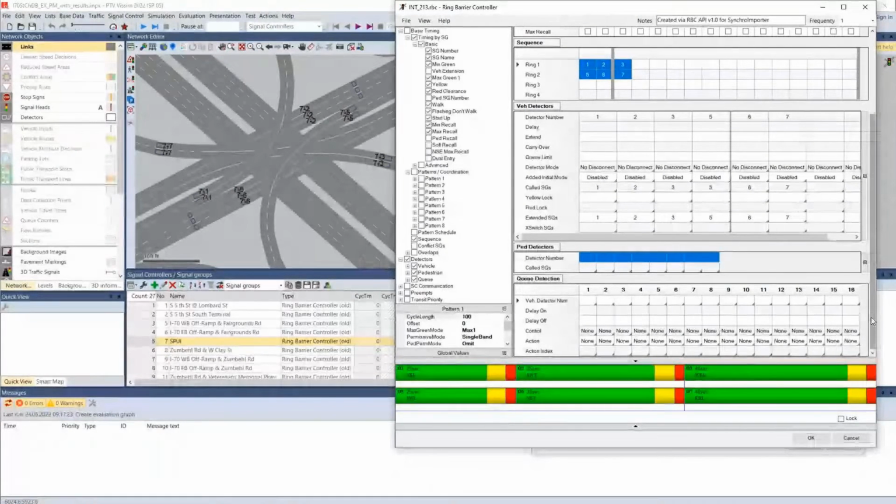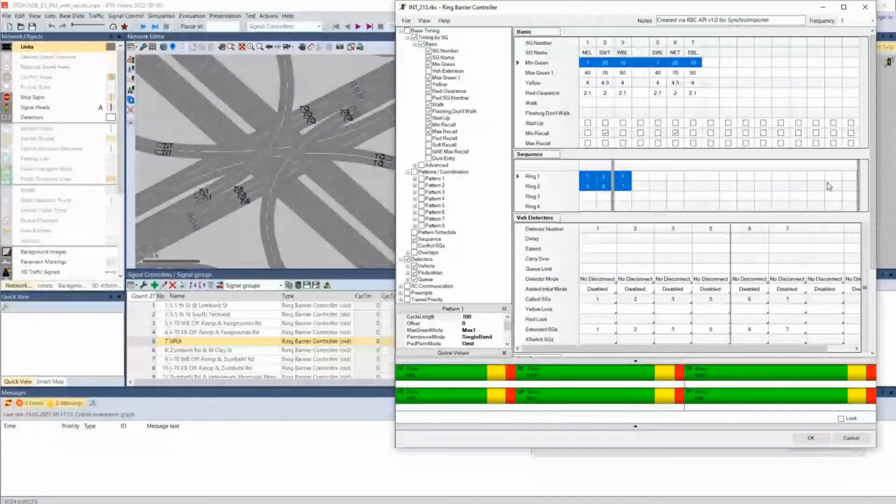And so basically what you're going to have to do when reviewing signal control is it's kind of a tedious process because there's not just a quick overlay that you can do. You're just going to have to pull up your signal timing plan and just validate that everything makes sense. For the most part, you can look at this diagram down below. It'll give you plenty of information about the splits and the sequencing, and then you'll just look for the cycle length and maybe some other specific things.